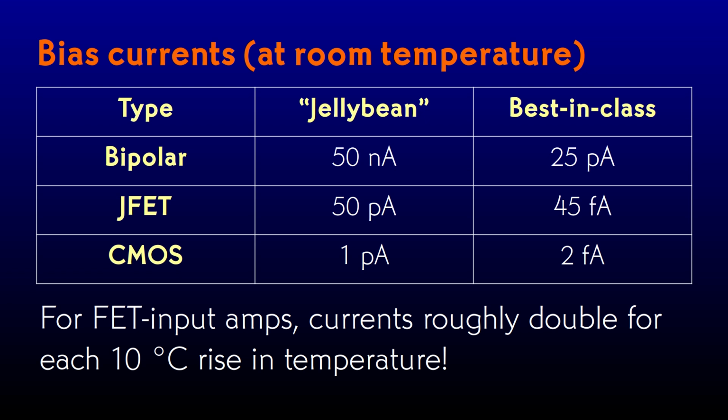Because I knew that bias currents might be an issue when I put this circuit together, I chose an LMC6482, which is a fairly low bias current CMOS op-amp, with rail-to-rail input and output, so that the low supply voltage will still allow a reasonable signal amplitude.